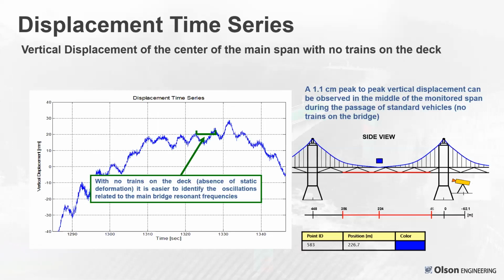We also looked at some background vibrations when it was just traffic and no trains. And from this, you can get the natural frequencies of the bridges just by being excited by wind or the traffic, truck traffic in particular.